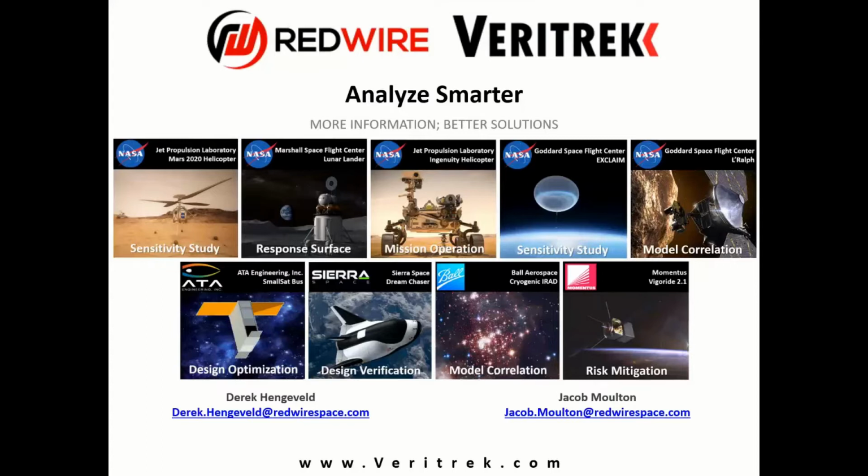Veritrek is a tool that basically plugs into Thermal Desktop and allows you to convert high fidelity Thermal Desktop models into a reduced order form. The reason that you might want to do that is whereas a Thermal Desktop model might take minutes to hours to days to run a single simulation, by converting that into a reduced order model using Veritrek, we can now run thousands of those simulations in a few seconds.